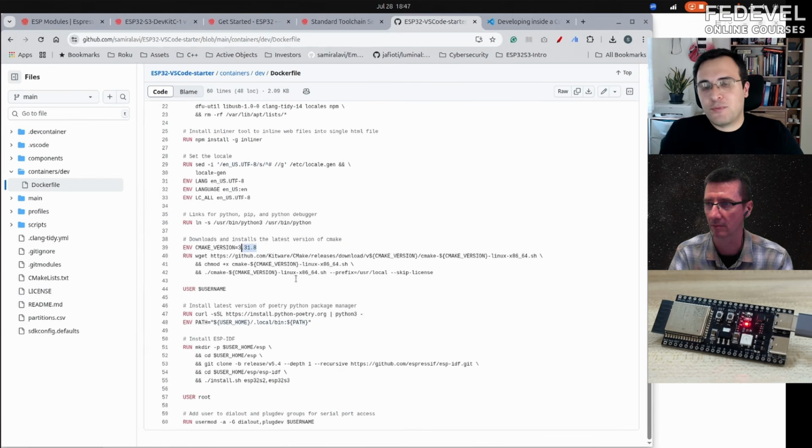And when you use, for example, workflows or automation, you want to make sure the application is developed with the same version that it is going to run with by the tests, if you want to run it in a continuous integration pipeline. And when you want to release the final artifact, which is the final firmware binary, you want to make sure it is built with the same versions. Because if it is a different version, it is going to break the tests, and later on you might face new bugs that you didn't know about in advance. This is quite important for any serious product.